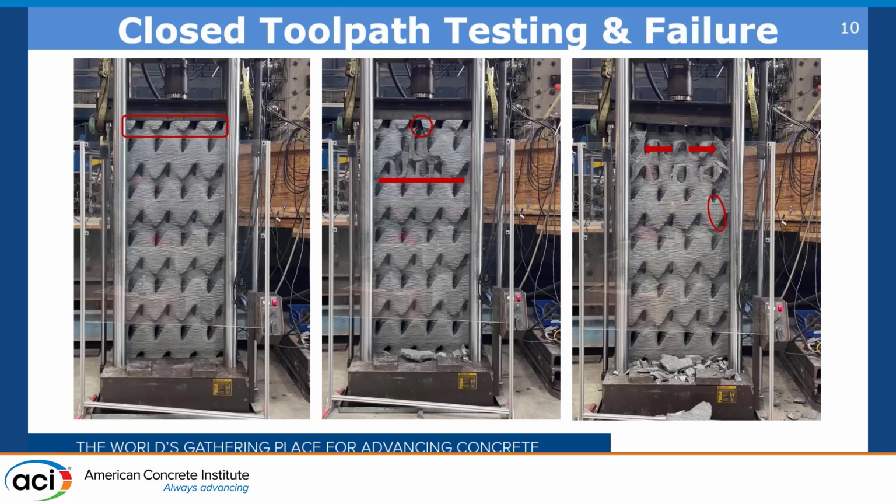The overhangs are due to a cutoff in the geometry, as we can see lower down, given the periodic nature of the gyroid, it's just a repeat over and over again. But where we cut it off here, you can see we cut it off there, there, there. And what this leads to is, instead of the gyroid being able to distribute across its entire geometry, we suspect there are stress concentrations building up in these overhangs that then lead to failure at the top of the wall before the rest of the wall can be properly loaded and lead to failure.